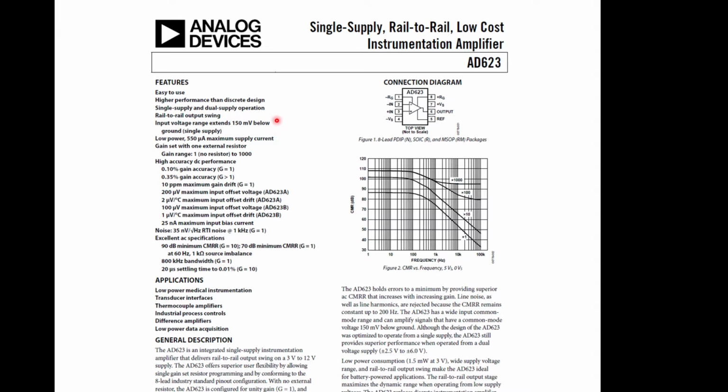And this sounds like magic, but that just goes to show, I think, that if you've got signals that are the equivalent of 0 going into it, you've got a chance of amplifying them. It's low power, and it qualifies that with 550 microamps maximum supply current, so it will take 550 microamps for each amplifier. In this case there's only one amplifier in the pack, so that's good. Low power, 550 microamps is reasonably low. It's not fantastically low though.